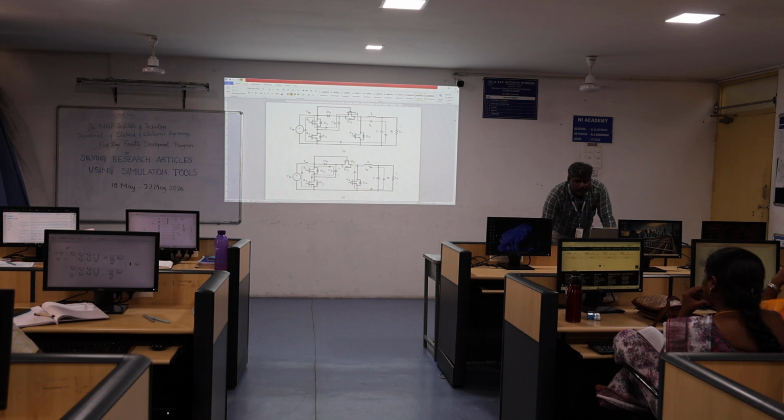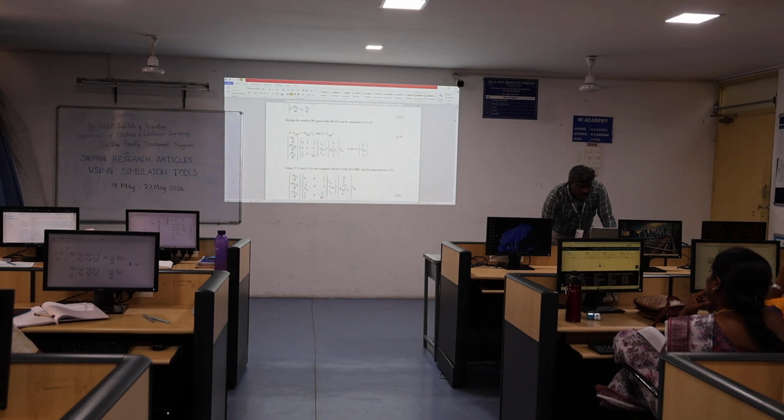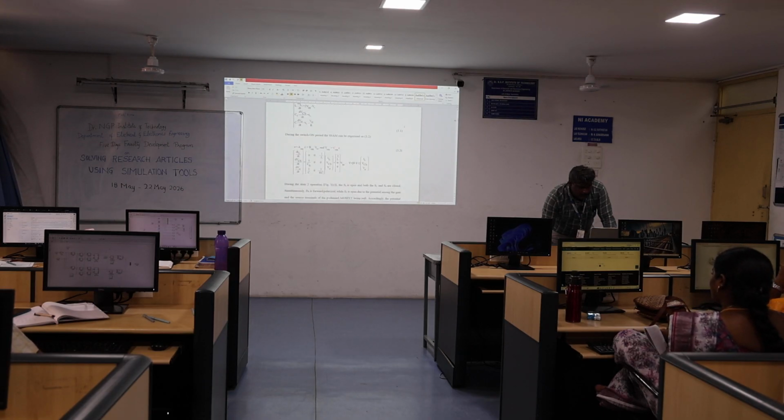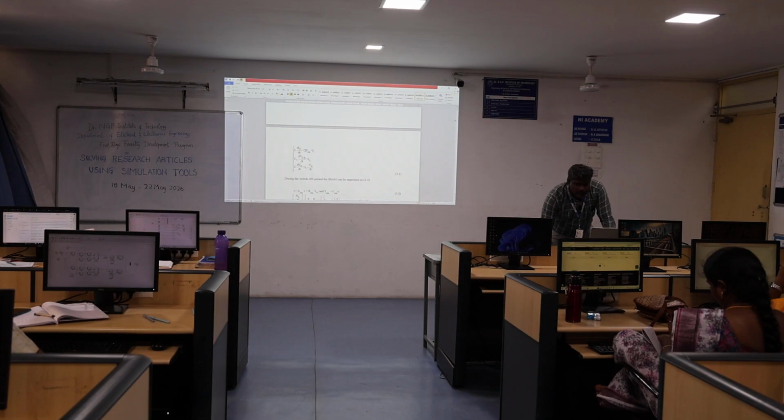Capacitor voltage is also input voltage. So next, another end is V0. Now you can write down the state equation during the on time. So this is the on time. I want to write down the voltage across the inductor, L into diL by dt. So input voltage plus capacitor voltage, one end. So therefore 2Vin minus V0. This is the first equation.